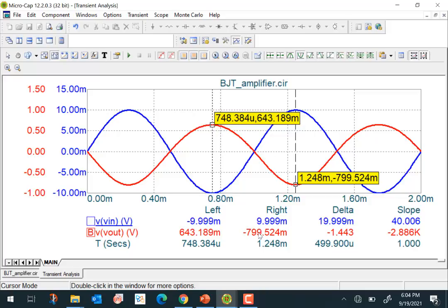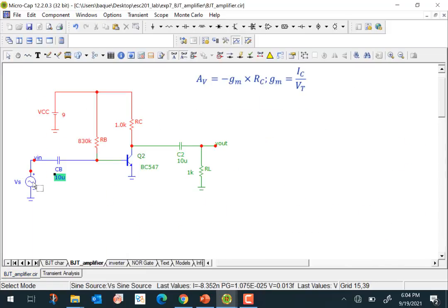Specifically, when you look at the base emitter side here, you have a diode and the diode's current voltage relationship. The way amplification is occurring is that this voltage goes to the diode here and it causes the base current to change. But the relationship between base current and this voltage is non-linear because it's a diode. And then that base current causes a collector current to change.